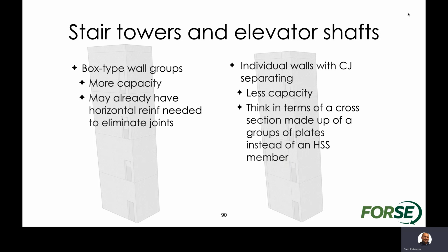You already probably have horizontal reinforcement near the openings and at the floor lines, and there's plenty of reasons for adding a little bit more horizontal reinforcement and eliminating those control joints and having a much stronger system design-wise.